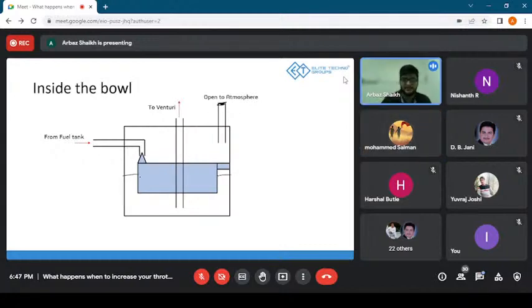Definitely. So, what would happen, let's take our original example. Say you have a glass of water with a straw in it, and you cap the opening of the glass such that the only thing going in is the straw, and you make it leak proof by putting seals around the straw. If you try to suck the liquid, it would not come out because there is no atmospheric pressure acting on the surface of the water. It's only on the top of the cap that you have put. So that is why we need an atmospheric opening, and as soon as you introduce this opening, it would work. The liquid would move upwards.